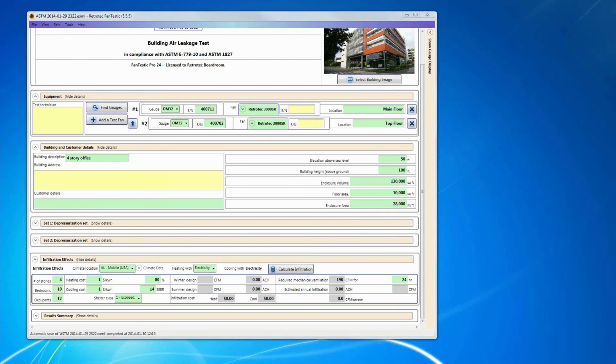Once we go into larger commercial buildings, the infiltration analysis for residences that we would use doesn't really apply much anymore, mostly because the HVAC system is a bigger determinant on the fresh air load than infiltration is, unless the building is really, really leaky. So the moment we get away from a residential house, the cost of infiltration becomes very difficult and complicated.